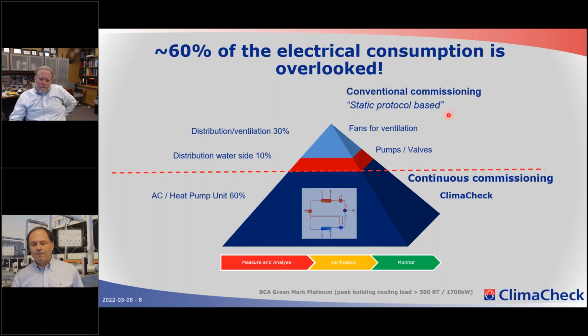But there is some focus on that. Why I started with this is that there is such a neglect of the heat pump or air conditioning and refrigeration system. It's assumed that it works as rated, and in reality, that is not the case. And this often represents 60% of the energy consumed by the system, and you still assume that it's working.